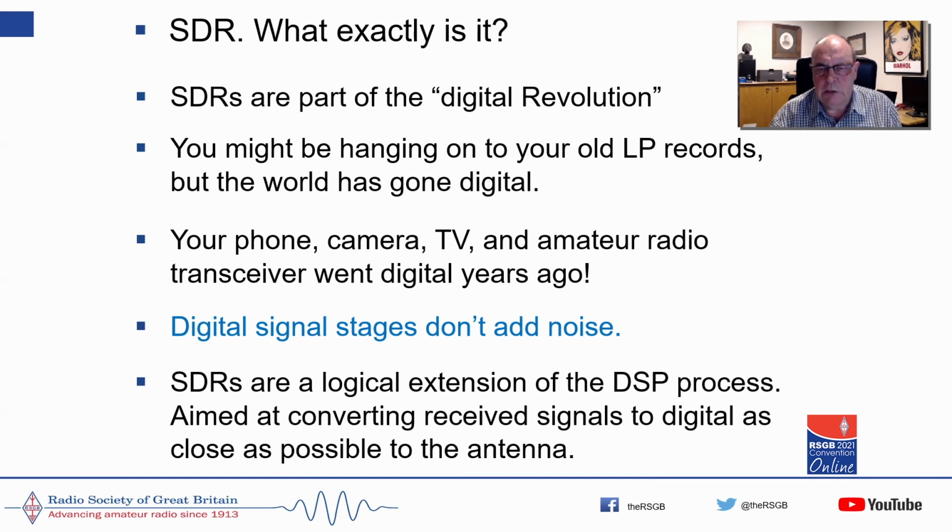And there are ways around it. They use randomization in the chips and oversampling, multiple sampling of the same data to average that out. So SDR receivers, they sound clean. When you first get one, you think, oh, this sounds a lot better than my old superhet radio. And the main reason for that is because the frequency down conversion from RF to audio is not adding any noise. So you don't get noise in the mixers or the IF amplifiers and things like that.